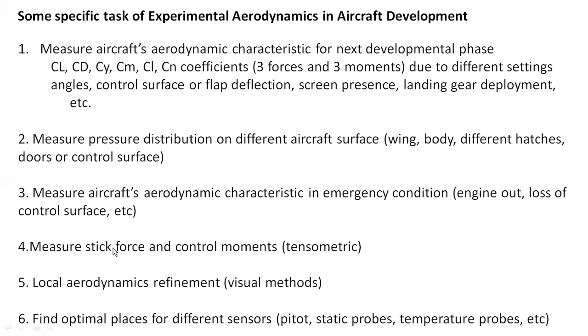Four is measuring stick forces. These are forces that act on control sticks, forces that the pilot experiences when moving the control wheel, and forces that act on the control system and control surfaces, forces that act on the aileron, on the rudder, on the elevator. As the elevator and stick are connected by control systems, these forces also depend on the kinematics of the control systems.